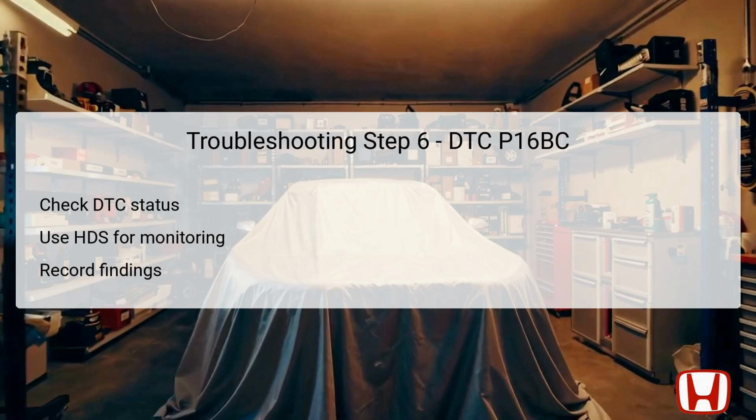If the DTC is no longer present, it could indicate an intermittent failure. This means the system is performing adequately at this moment, but the problem could reoccur. Therefore, it's vital to go back and check for poor connections or loose terminals at the alternator once more. Each diagnosis step builds upon the last. Thus, thoroughness in every check is paramount.